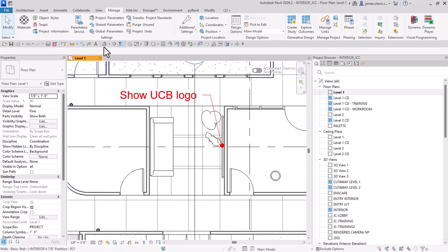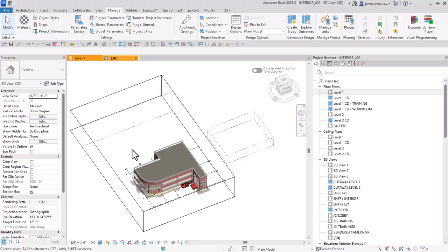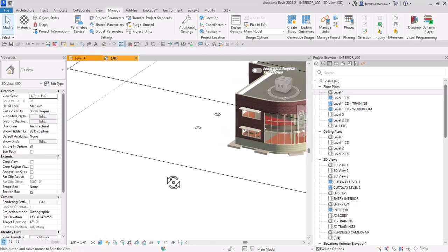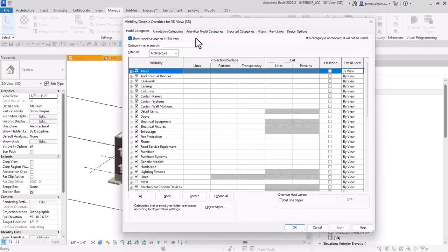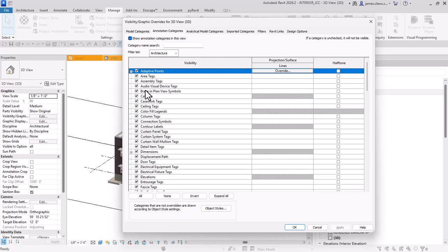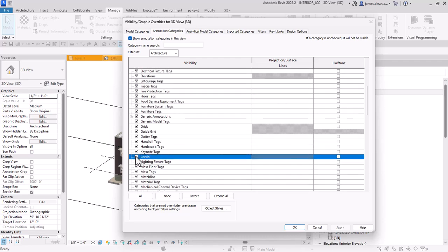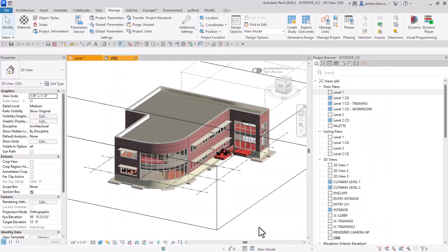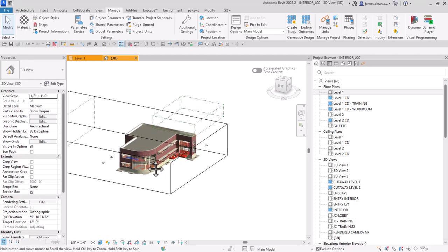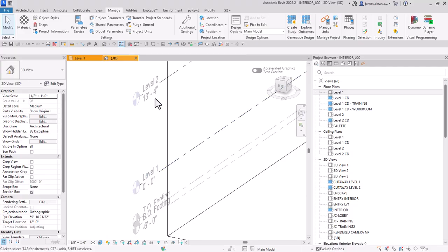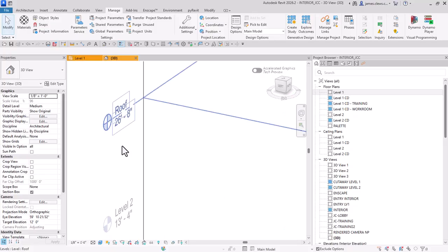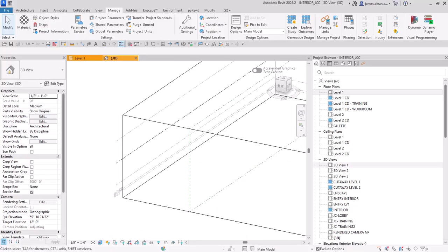The interior levels, so I looked at the model and confirmed that, if I go to levels in here and I was displaying them, because the shell had the floor height set at 13 feet 4, I wanted to make sure that the levels inside the interior were also set to be 13 feet 4 apart. Again, most people had that.